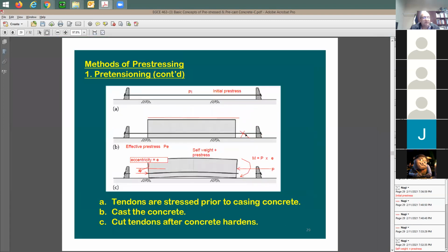Now, the question is, when do you think we're going to be cutting this? After the concrete cures? Yeah, by how much? Do you want to leave it 28 days? No. Usually concrete reaches the full strength at 28 days, right? If you ask the precaster, they want to cut it right after they pour the concrete, because they need the space, they need the yard, they need to cast more concrete, right? They need this bed. This is like a big cost for them. This is going to be their only workspace. So they'd like to put the concrete here, cut it, and take it out.